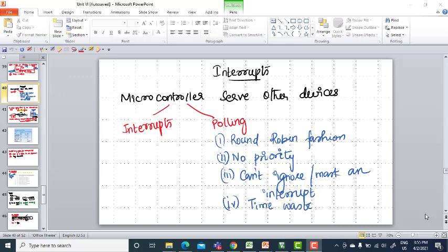And in case of your timer, you have held up your microcontroller in monitoring your timer overflow flag. That is the disadvantage in the polling method. But that won't be there in your interrupts. That won't be there if you follow your interrupts. You have six different interrupts.